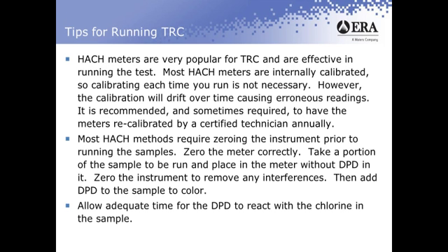That will be shown by waiting an additional minute after you take your reading, and if that chemical has weathered, your readings will start to rise. Then I'd recommend waiting another minute until you're seeing consistent readings, and that will let you know the reaction has come to completion. This way, you avoid reporting low residual chlorine results if the DPD chemical happens to be weathered.